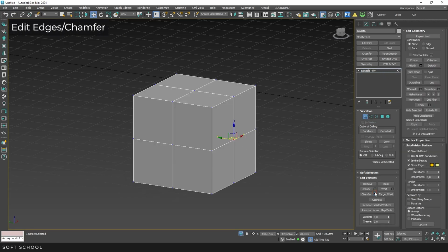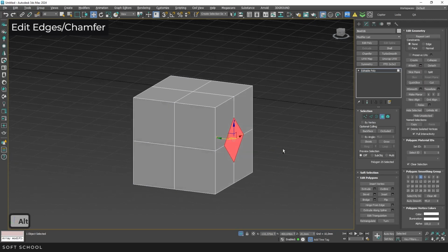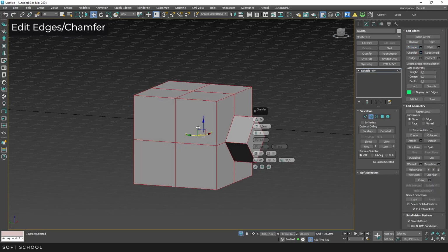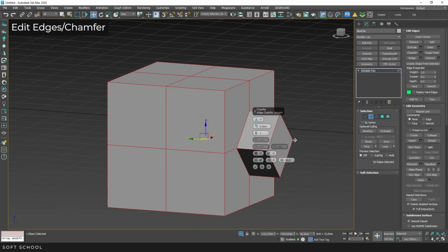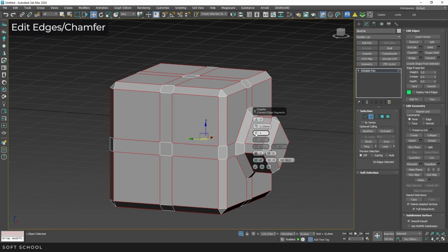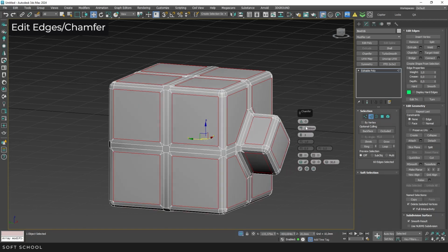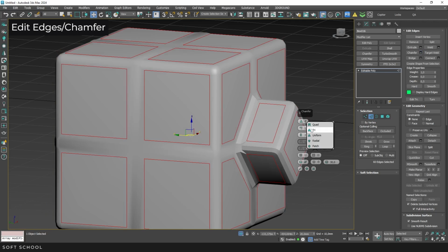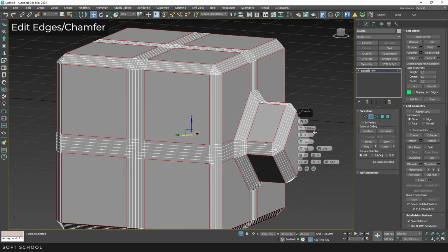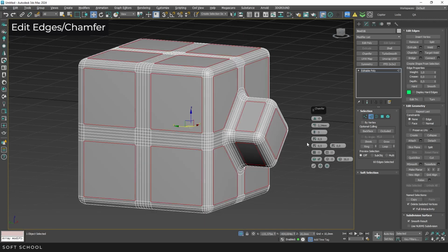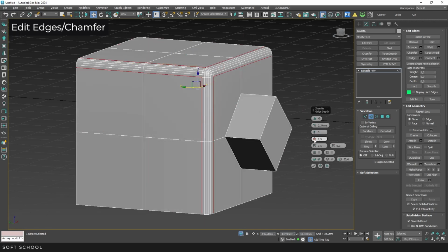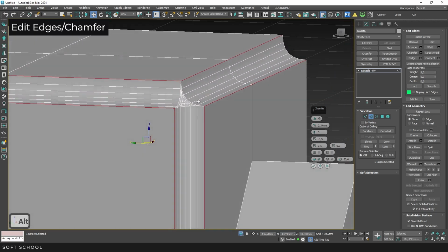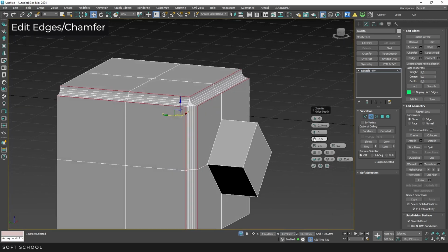The chamfer tool in the edge sub-object has many applications, each with its own features. We will cover only a few basic scenarios to get acquainted with the tool. For example, triangular chamfer is most convenient when we need just a bevel without adding smoothing and additional edges. In this mode, adding edges can cause problems in some areas of the mesh, which can be fixed by enabling smoothing. In such cases, a square chamfer is needed, which works more predictably, but requires attention to smoothing groups, noticeable only at the shading stage. Uniform is set by default, works like the quad, but also allows creating a negative radius. There is also a cut function.